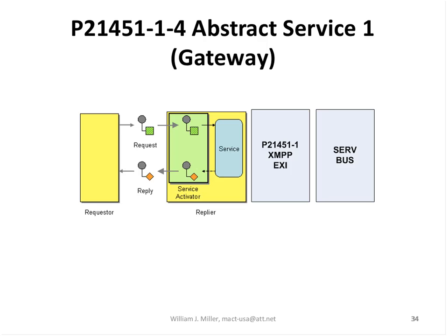So if your service bus resides, we'll say, in a gateway or connected to a gateway, for example, like Zigbee or Z-Wave or something that has an access point. It may even be connected to a Wi-Fi device using 802.11. You're communicating to whatever sensors that are connected to that device. So an adapter can be added to the gateway, collecting that information, converting it to XMPP, and now you have all those sensors connected so that you can share it. Next slide.